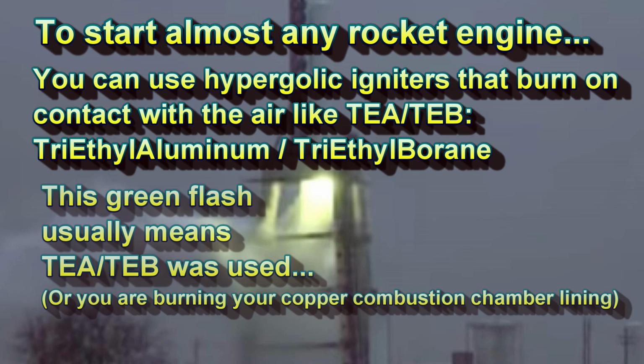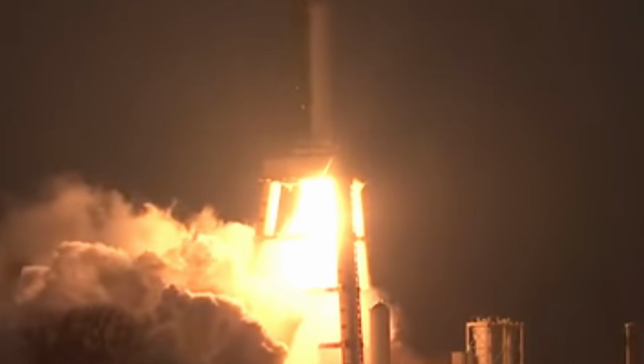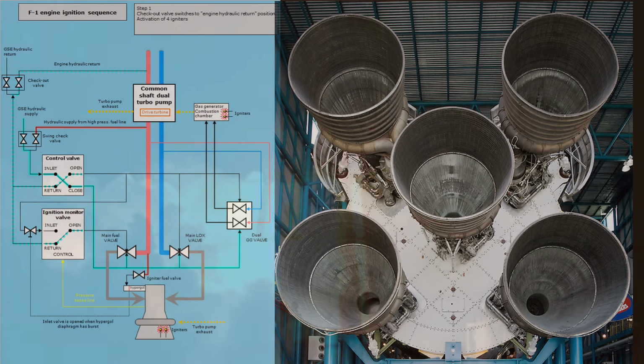at a high temperature on contact with oxygen in the air. Two of these chemicals are triethyl aluminum and triethyl borane. These can be combined and are called T-Tab. These chemicals explode with a green glow and were used to start the Saturn V F1 engines. Here is the ignition sequence diagram for the F1.